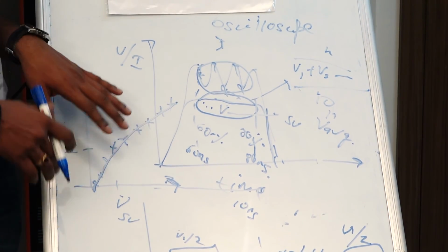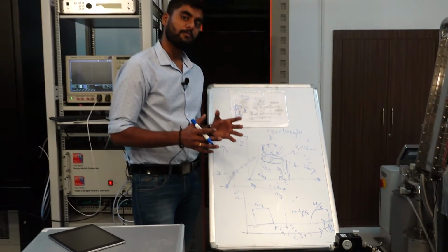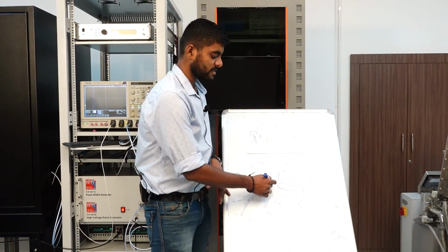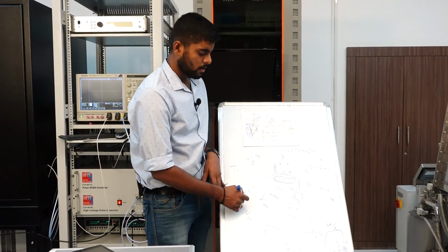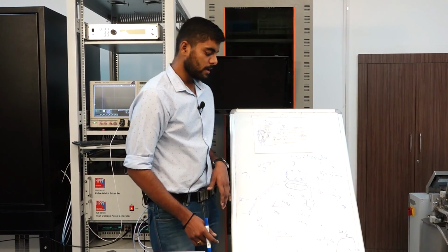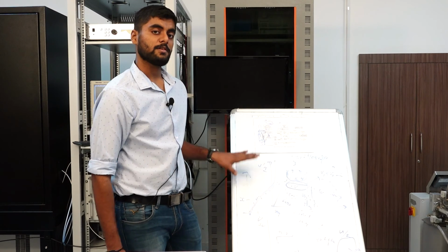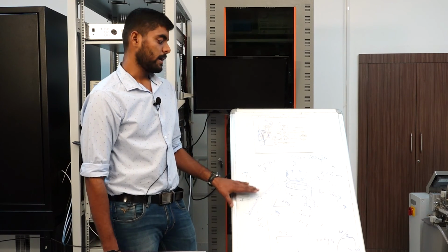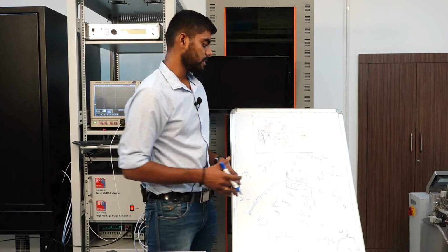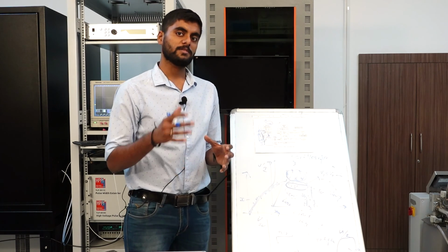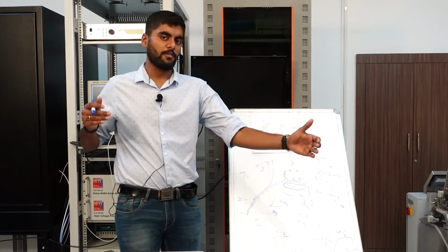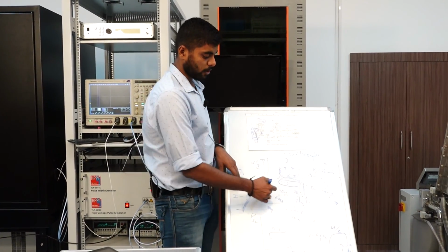That's important because this characteristic gives you a lot of broad information about the device under test. You can show your device degrading, your device saturating, your device having a higher current over different voltage ranges. It gives you a broad range of information. Instead of going into the very specifics of the voltage waveforms every time, you can broaden this up and show the whole range of information in one shot, and that's why this averaging is important.